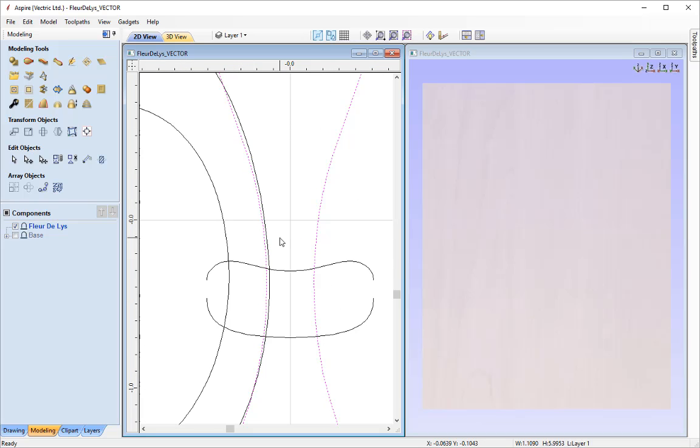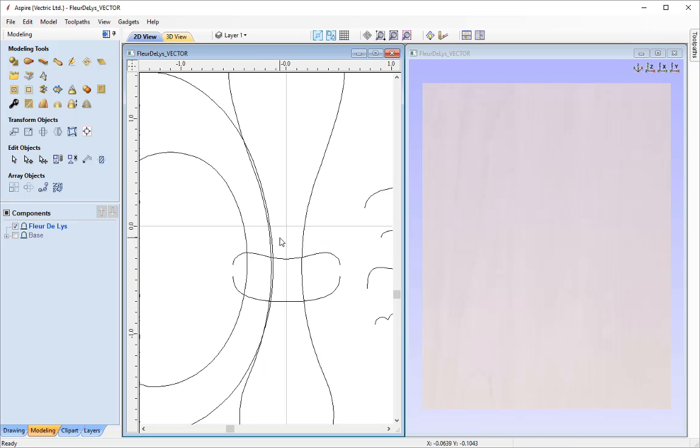Now this isn't a mistake, I've done this on purpose, as I want to create an overlap when I'm creating these individual components, so that when in the component tree I put them in the combine mode of merge, they create a seamless flow into one another. If I didn't do this and I created two lots of vectors that were flush against each other, I am likely to have slight little gaps in between each of the two components, and that is going to cause problems when it comes to machining.